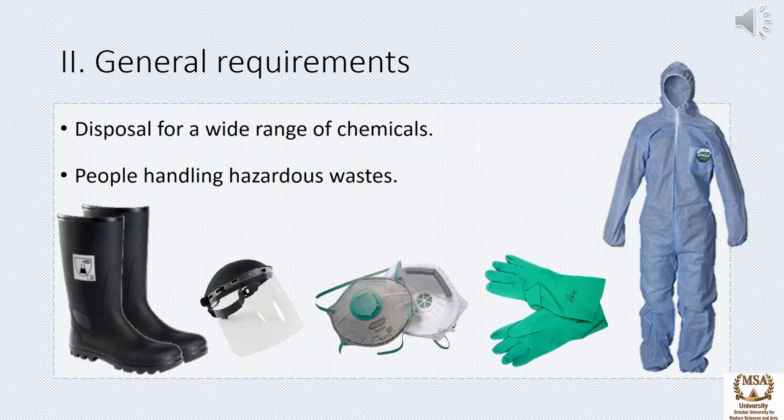General requirements. Disposal is necessary for a wide range of chemicals which possess an inherent health risk and environmental hazards. However, the quantity or the method of treatment might be different. People handling hazardous wastes from segregation to disposal should be supplied with suitable protective gear, including face masks, boots, and hand gloves.